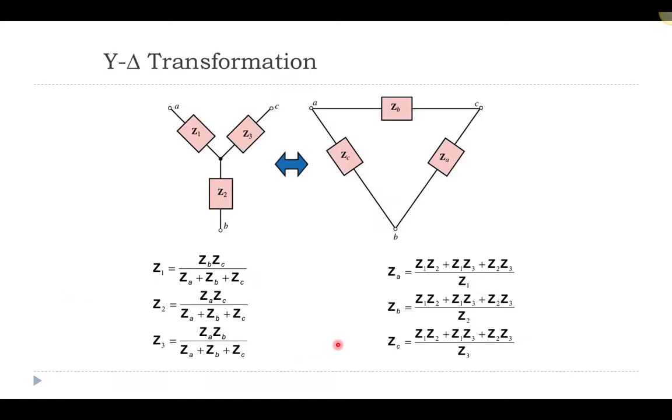In this presentation, we consider another method of analysis for AC circuits, and specifically we're going to look at the superposition principle in detail, and we'll mention Y delta transformations. You may recall in DC circuits where you had resistors not connected in series or parallel, that across three different terminals, like A, B, and C, if you had a configuration that looked like a Y, you could convert it into a delta across those same 3 points.